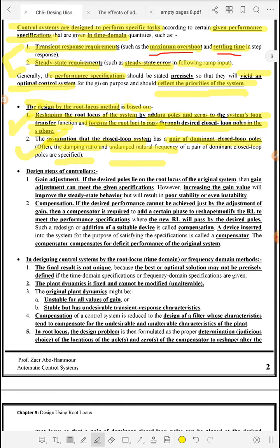So what are the design steps of controllers in root locus? In the design process of any controller, whether using root locus, bode plot or PID controllers, we should start with the simplest design scenario, and if we achieve our goals, then there is no need to go to a more complex design process. If simple design can achieve our goal, we should stop.